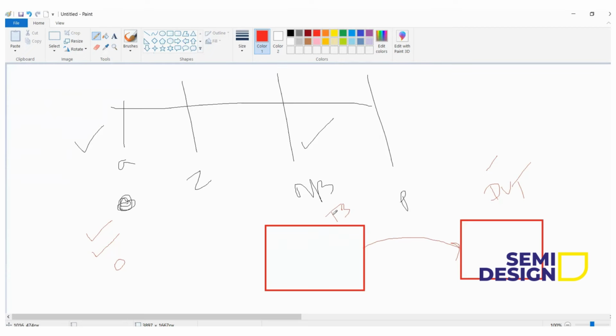In my tool, maybe the test bench is executed first and the DUT second. According to that, I have adjusted my verification environment and written the code. When I run it in a different tool, the DUT is executed first and the test bench second. Then I may get different results. So I have to make sure the order of execution is constant for every tool. In Verilog, it is not possible because I am writing both inside modules.